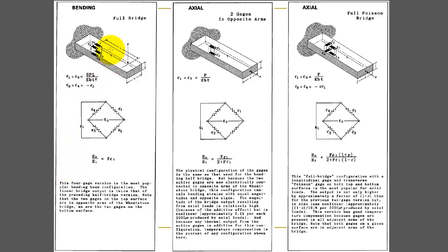Well, it's this type of configuration, producing a linear output, 4 arms of the Wheatstone bridge, and you might connect this to the load cell that you used in the first big assignment for this class. The load cell had 4 strain gauges connected in a bridge arrangement, and it was done to provide a nice linear output on that beam between the bending of the beam and the voltage output.